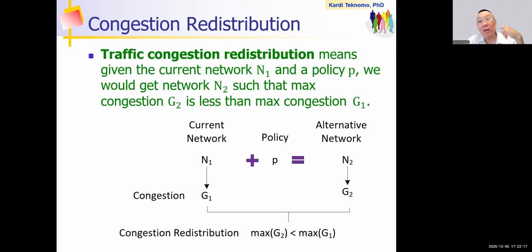But I'm telling you, travel demand management is good. But what if you can also change the way of thinking? What if you change the supply to change the demand? The supply means the road network, the road width, the number of roadway lanes, and probably the number of public transport that you have. Remember, the demand is from the population side that creates the flow. The supply means the infrastructure. So the question is, if we change the supply, probably it will also affect the demand.